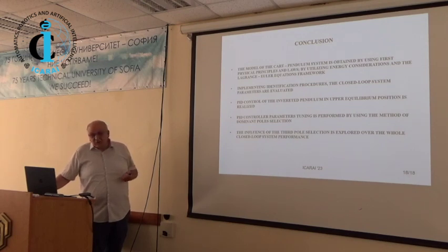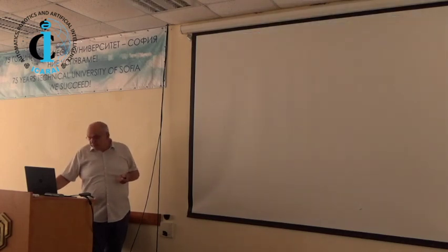And finally, we tune the PID controller based on the criterion of dominant pole selection, showing the influence of the placement of the third pole of this closed loop system on the system performance. So, thank you for your attention.